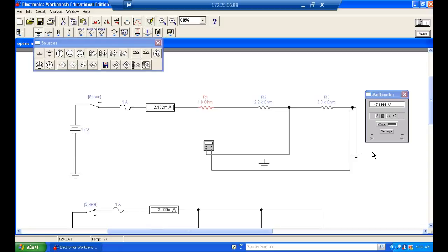You ever did that? Series string, find the one that's open. It's hard to do, guys. Normally what I do is just get a good bulb that I know is good from another string, and I just start swapping it down the line until I find it comes back on.